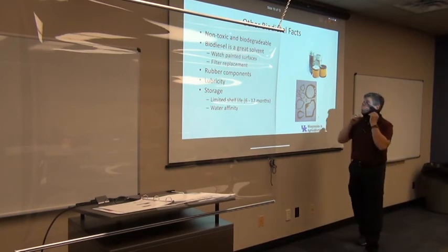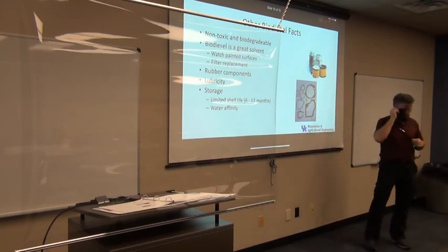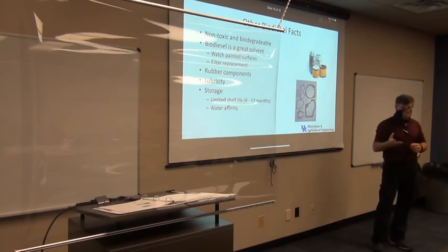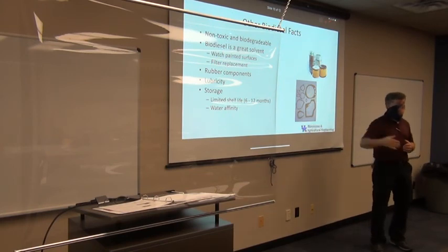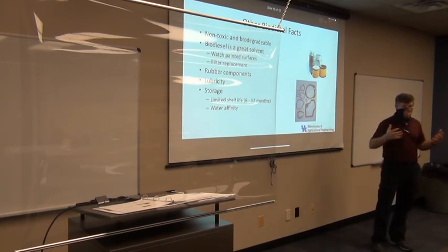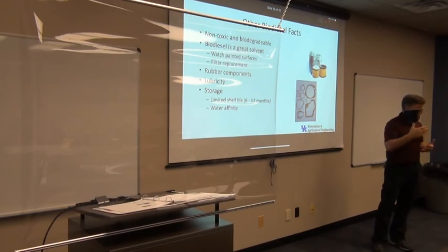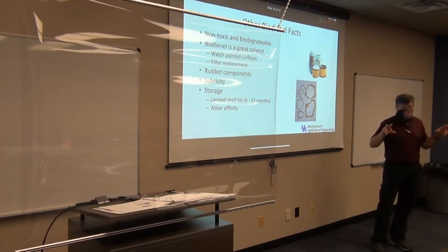Storage: biodiesel has a limited shelf life. Any fuel has a limited shelf life. And the more alcohol, the more ethanols, methanols that we put in our gasoline, the more biodiesel that we put in our diesel supplies, those oxygenated fuels have a very high water affinity. They like water, so they will pull water in. And then they will have that oxygen from the water that will react, and essentially the fuel will rust.